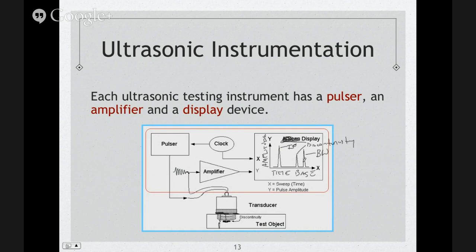And we know that our inspection area would be from an interface, meaning our front surface, to the back wall of our material. So we're inspecting anything that's in between those lines. So any spike you have in here is a reflection of sound within this surface and the back wall. Okay.